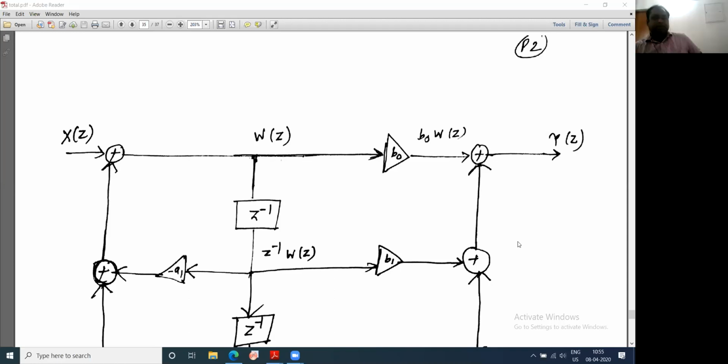This is the advantage of digital signal processing over analog signal processing. In analog signal processing, you have to realize everything separately, and separate blocks are there. Different kinds of amplifiers are there. You have studied in analog design the logarithmic amplifier, the logarithmic multiplier, another kind of multiplier, but that is not required in a digital system.